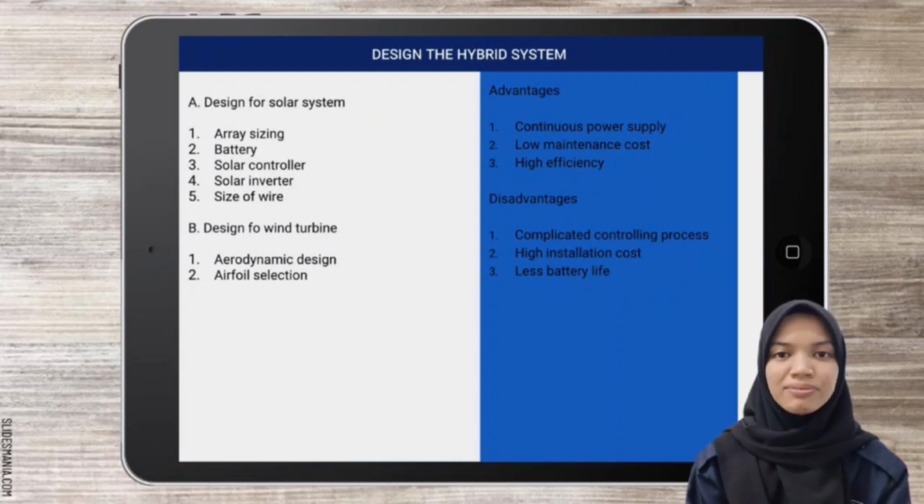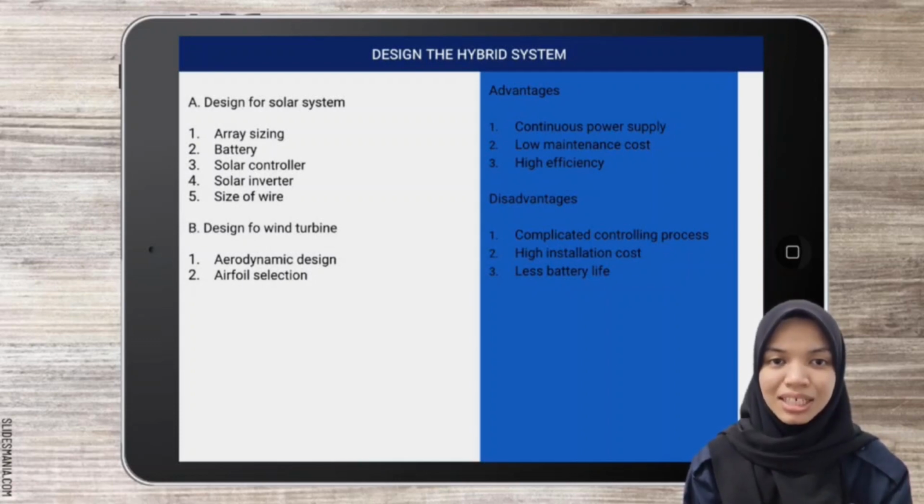Solar controller. To prevent the batteries from overcharging, a controller is used. It is very important to keep batteries within a safe range. The controller to be used should prevent feedback current from batteries to the photovoltaic cell module and turbine. Solar inverter. It is the device that is meant to perform the operation of converting DC into AC. It should restart automatically and switch off if the array voltage is too high or too low. It should also have a constant charging system and a load status indicator.